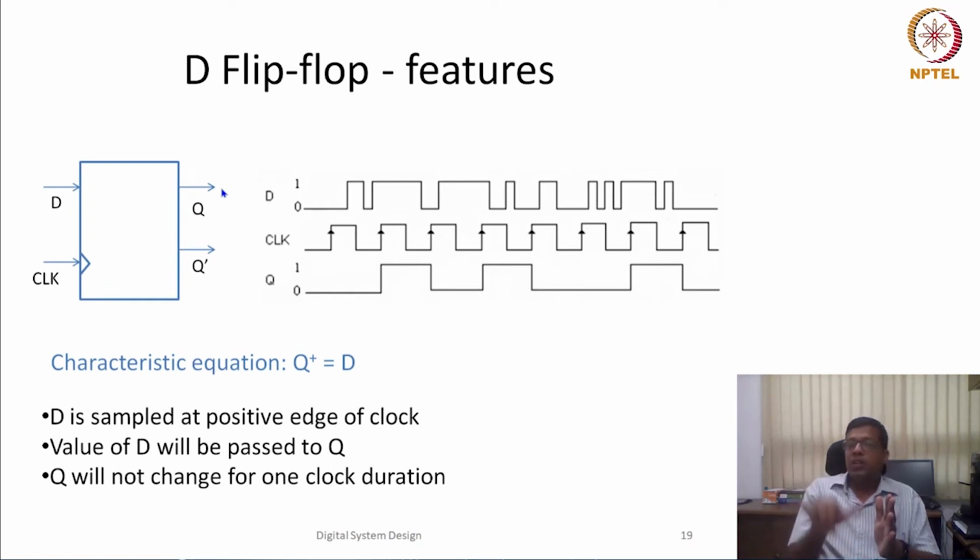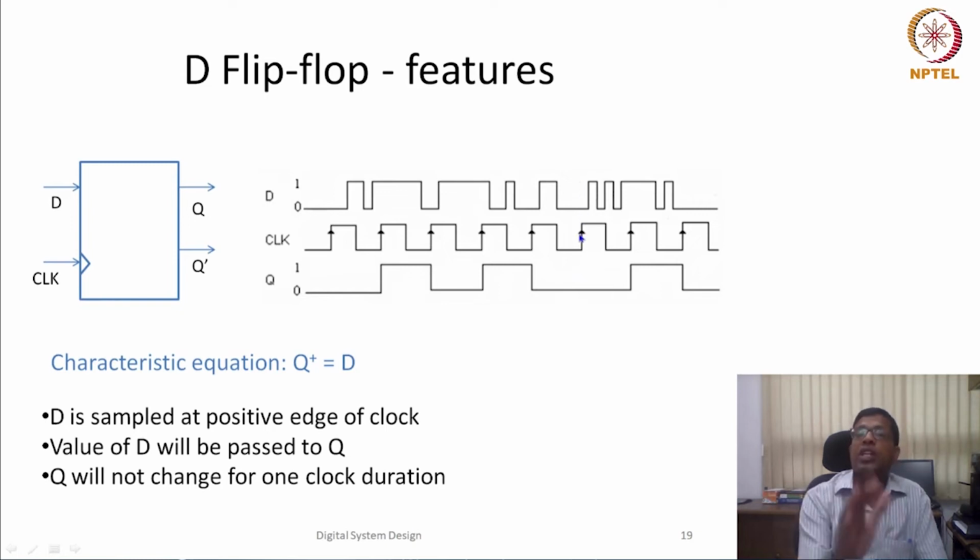Only at the end of 35 units of time are we sure that the output will not change further. So this fluctuation can keep on happening, but whatever the output of the adder is at 35 units of time, we can sample it at the correct time.